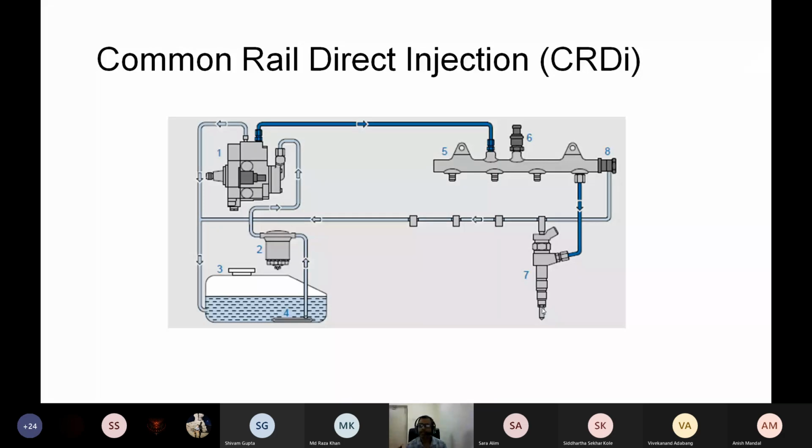Then we stopped at the point of discussing how we can vary the fuel injection pressure, from 200 bar to a maximum pressure that depends upon the hardware and software capability of the fuel injection system. Normally it is more than 1500 bar, or up to 2000 bar.